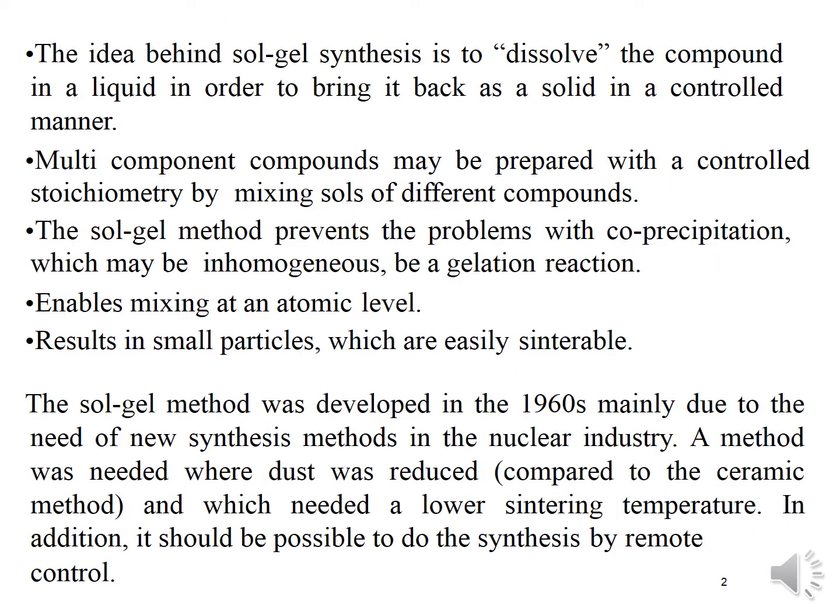The idea behind sol-gel synthesis is to dissolve the compound in a liquid in order to bring it back as a solid in a controlled manner. Multi-component compounds may be prepared with a controlled stoichiometry by mixing salts of different compounds. The sol-gel method prevents the problems with co-precipitation, which may be inhomogeneous. The gelation reaction enables mixing at an atomic level and results in small particles which are easily sinterable.